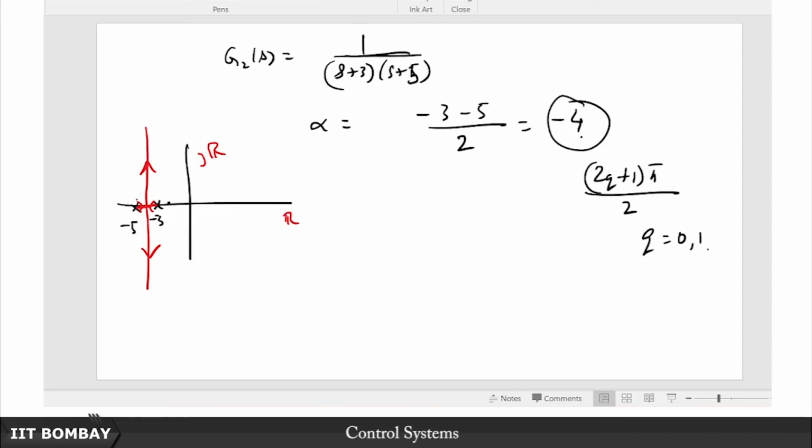So in this case, you notice that I have no fear of the closed loop poles migrating to the right half plane. So in this case, it turns out that I can actually keep increasing k to as high values as I like, without any fear of losing my closed loop stability. Okay, right. So this is an interesting difference, and you'll immediately observe that this difference is arising out of the relative degree of the plant. Because of the relative degree and the location of the centroid on the strict left half,